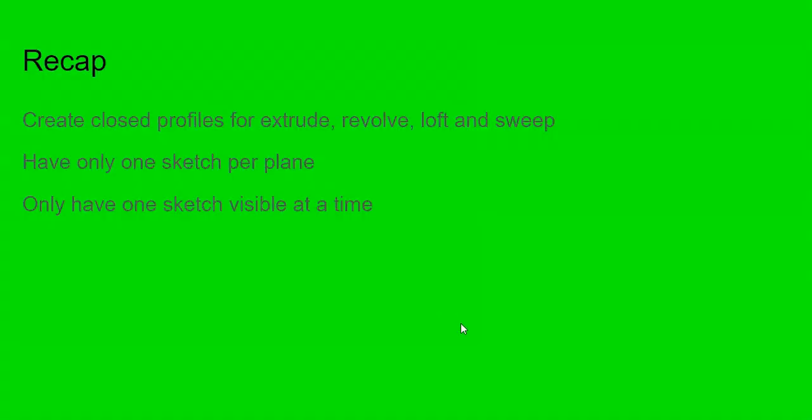Okay? Recap. Closed profiles are needed for extrude, revolve, loft, and sweep. Have only one sketch per plane, and only have one sketch visible at a time. Pretty simple. Just ways to avoid confusion and trouble.